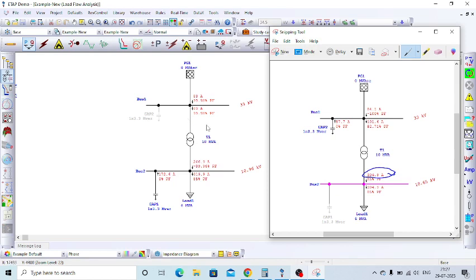So when comparing the power loss, the 304 ampere current will increase the power loss. As we know, the power loss PL equals I squared R. In case 1, the current is 304 squared multiplied by R. In the second case, it is 266 squared multiplied by R.